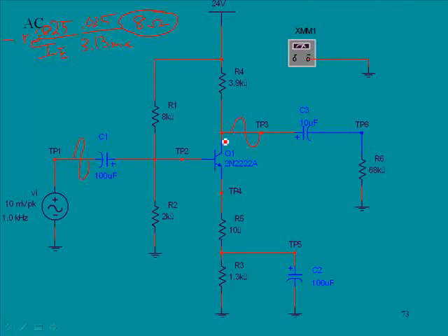It is going to see through this cap this resistance over here of 68K. But for AC, it is going to see this as a common point as well. So the AC signal can go this way and it can go this way. So the resistance that it experiences is actually the parallel value of 3.9K and 68K.